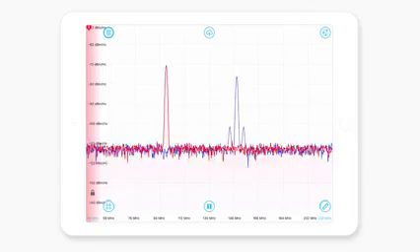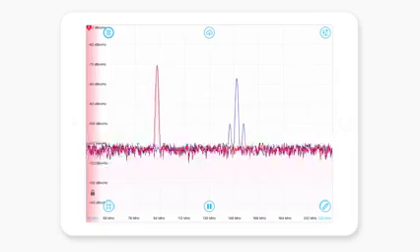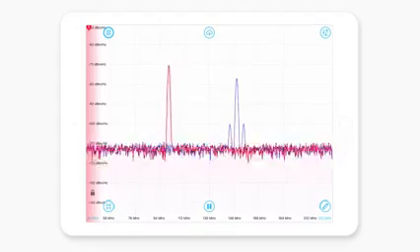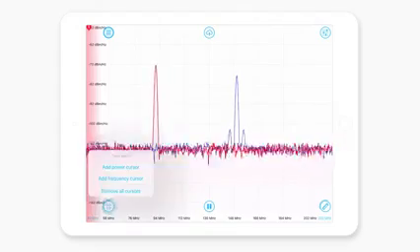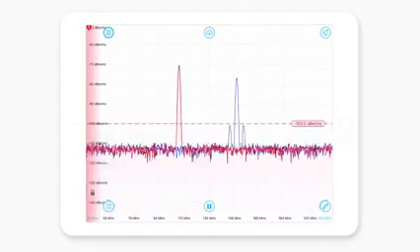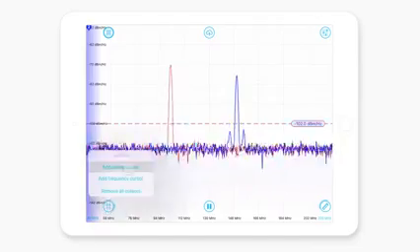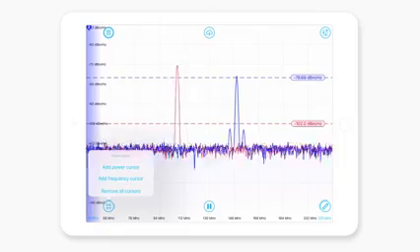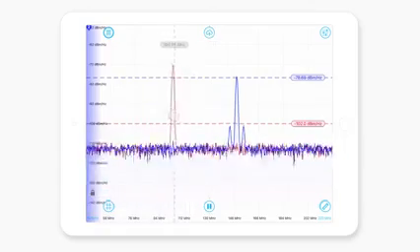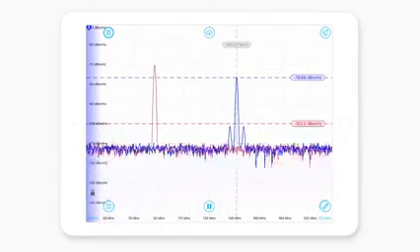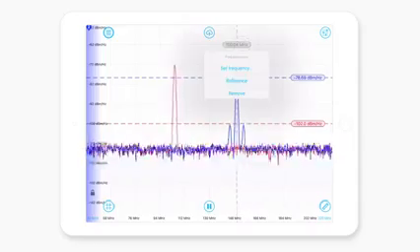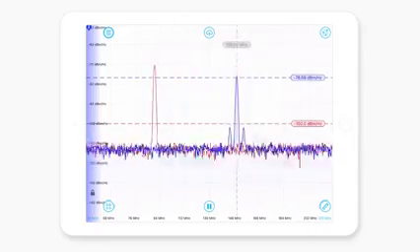So you may have noticed earlier that I dragged some cursors into the measurement window. MokuLab's user interface makes this trivial because you just tap this icon here and you can add a power cursor. If I tap the blue trace and add a power cursor, it'll add a different one there. I can add a frequency cursor, and this is obviously common to both of the traces here. So I'll just set that one. I might set that one to 150 megahertz.